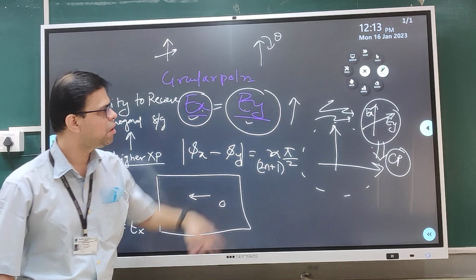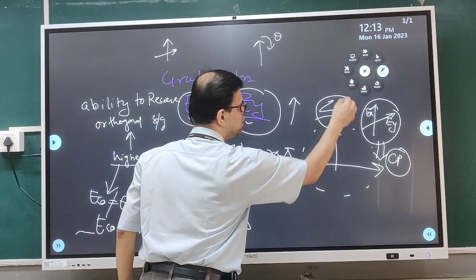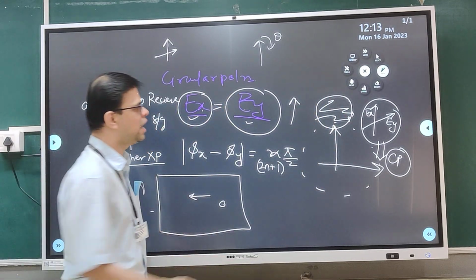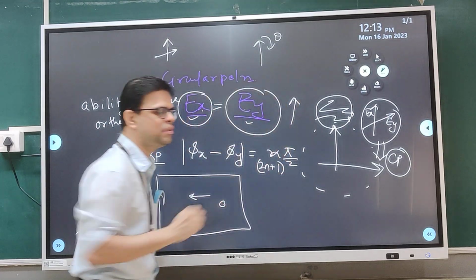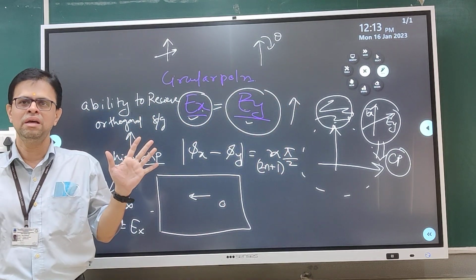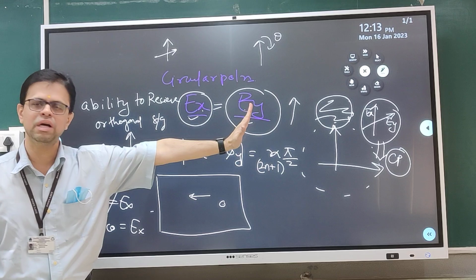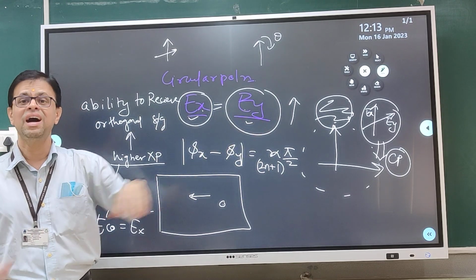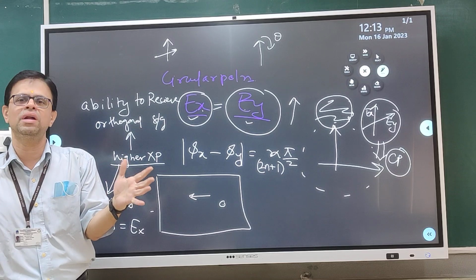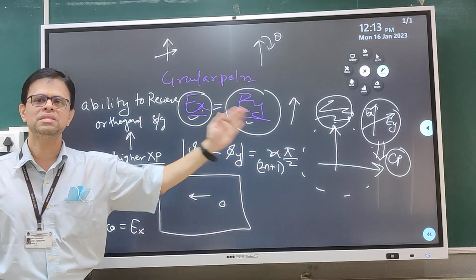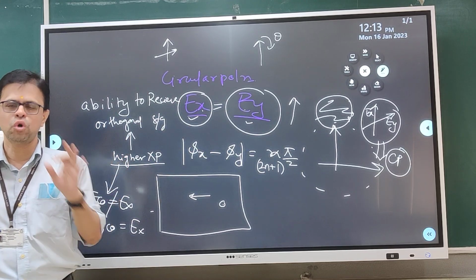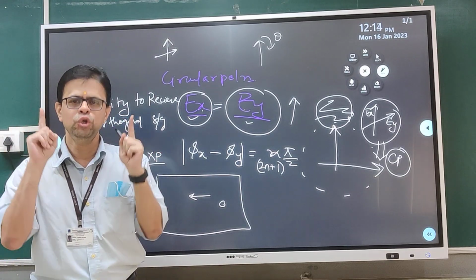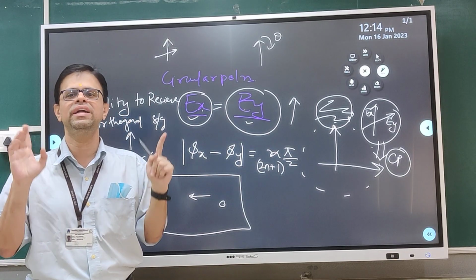So irrespective of the multipath propagation effects in the wireless channel, and even if the polarization of the transmitter is vertical, because the two cross dipoles ultimately realize the circular polarized condition, I will receive a signal. So in a nutshell, to design a circular polarized antenna, you should have a high cross polar antenna design.